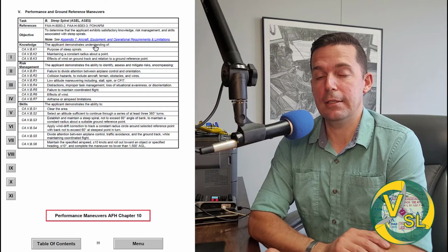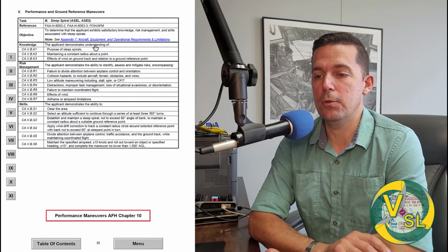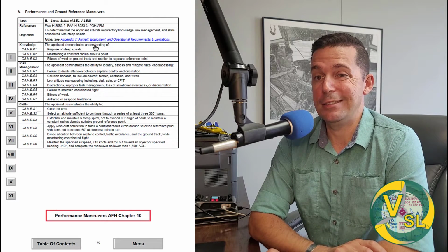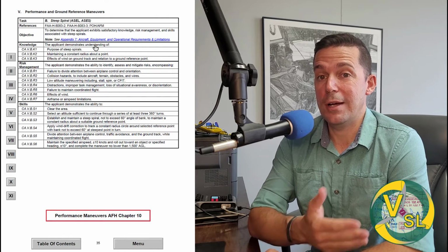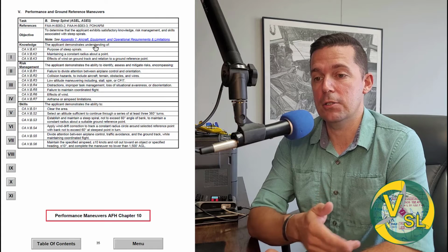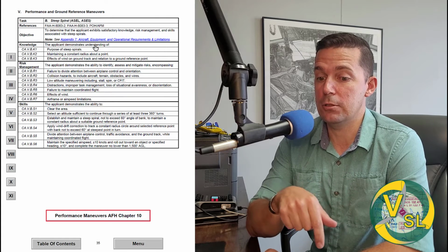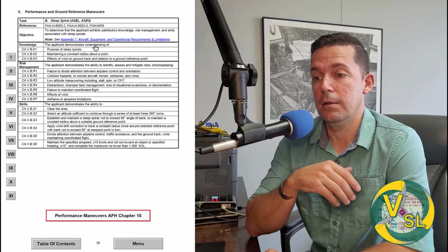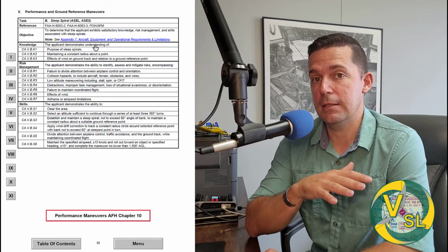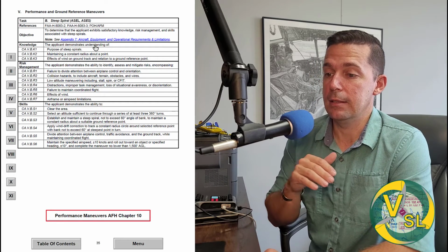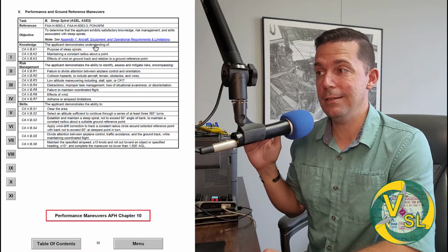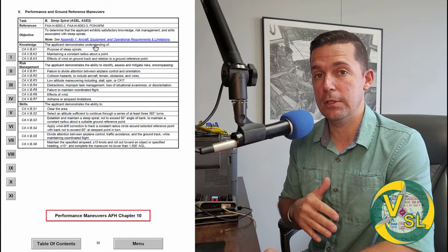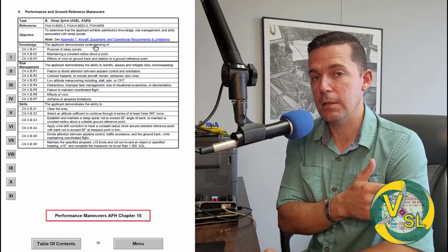I'm going to glide directly to the airport, and I'll probably arrive over the airport at 6,000 to 8,000 feet, depending on the airplane I'm flying. Much too high to start a traffic pattern, so I'm going to start a steep spiral and just slowly spiral down, staying over my desired landing point, and I'm going to complete the maneuver at about 1,500 feet AGL, ideally on a left or right downwind, kind of abeam my touchdown point.